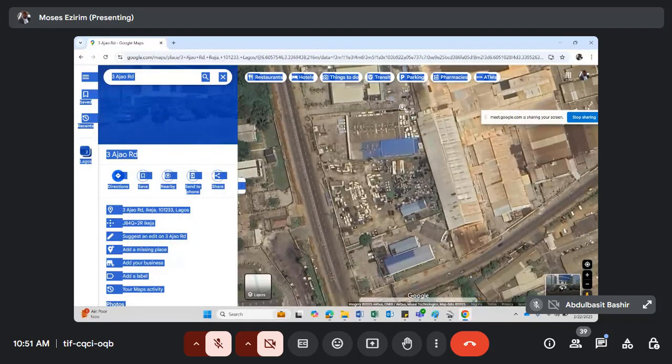All right. So now, once you can see the roof, now I want to measure. This is the ridge. I want to measure the area of this side here. So you need to come to the edge of the roof. From the edge of the roof, right click.